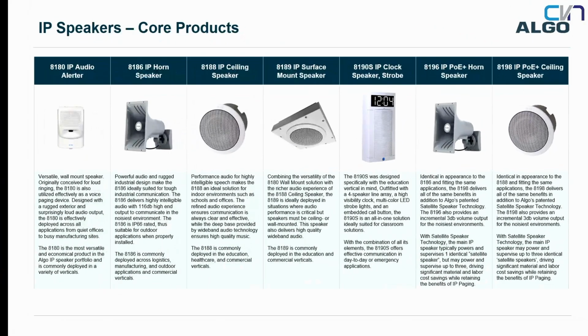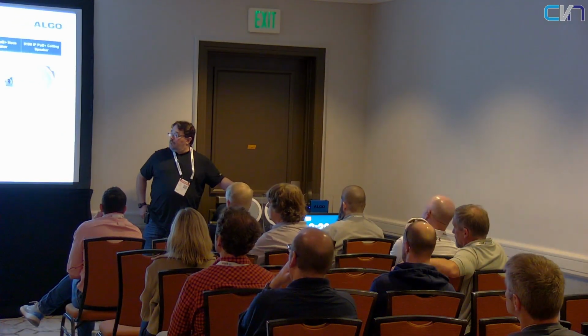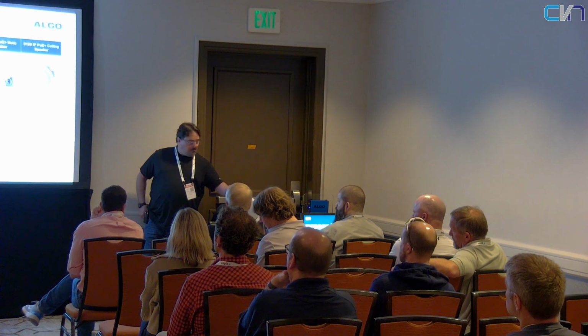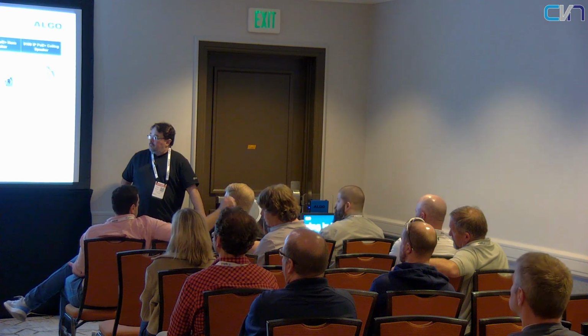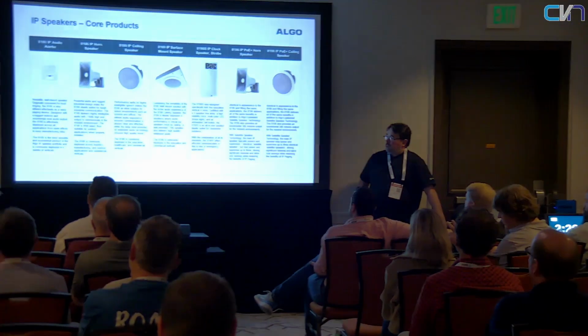It's just a single drop, and then it's an RJ45 patch cable in and out to the speakers. And these are 98s, right? That's a 98 right there. You can't see it on the back, but it's got dual RJ45 ports, and we're PoE to this one, and then we daisy chain to this one. So that reduces the number of direct LAN drops and data ports, and the satellite speaker is fully supervised off the host, but because it's not a full IP endpoint, it's less than half the cost. So it significantly reduces the cost to implement IP.